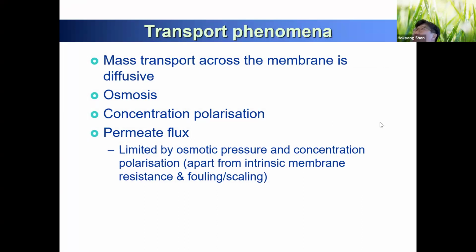So that's how we create the polyamide RO membrane, and then you put it into the element, like a spiral wound type of module and element. This one has around 40 square meters of membrane surface area. One module costs almost $200, and it can produce around 200 liters of desalinated water every day.